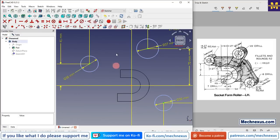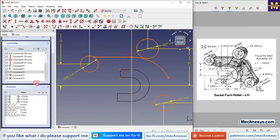So first thing which we will do is to project the geometry. We will project this, and this, and from here we will select a line tool and create a line, and we will select a 3-point arc and create an arc, and select this and this and add a tangency, and now we will select this and this and click on the merge, and let's see what is the conflicting.